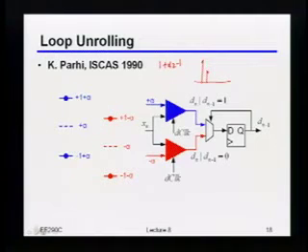The idea here is a lot like a carry look-ahead adder in the sense that, again, we'll assume that we knew that the previous bit was a 1, or assume that we knew that the previous bit was a 0. Well, in either one of those cases, I could just statically shift the threshold of the comparator to eliminate the ISI that those two cases would have seen.